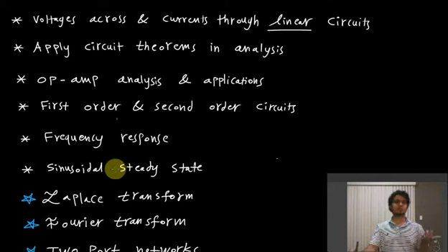For transients, that's, for example, when you have, say, an RLC circuit with a switch and a voltage source, and you turn the switch on and off in a certain manner. And the transient in this case refers to the voltage or current waveform, which can be abruptly changing. For example, if you have an inductor, we're going to see later on that what it likes to do is maintain the current as steady as possible.